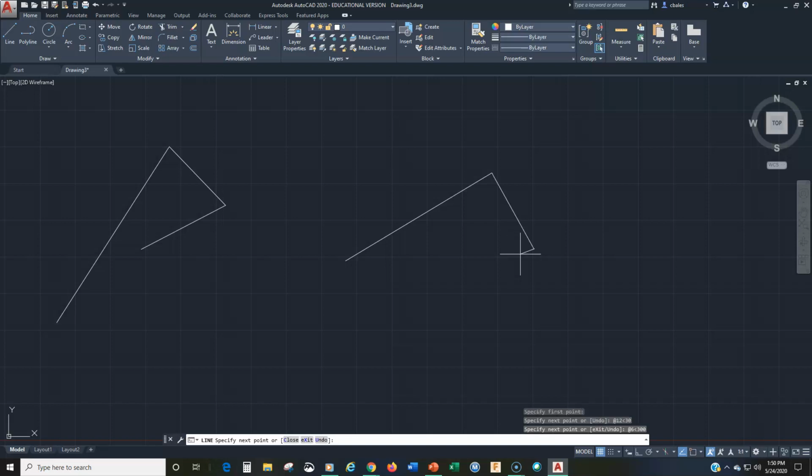Let's see how close I am. Oh, not too bad. The angle was a little bit off. Probably was closer to 25 degrees. All right, so now if I want to move back like this, let's say that distance, again, @10, that's about 10 units long, at an angle of, now what angle is that?